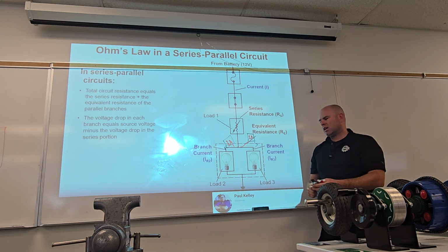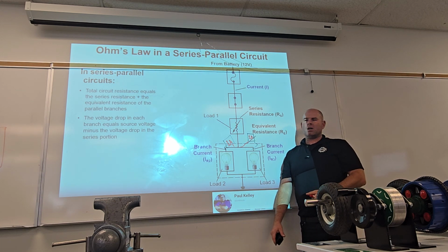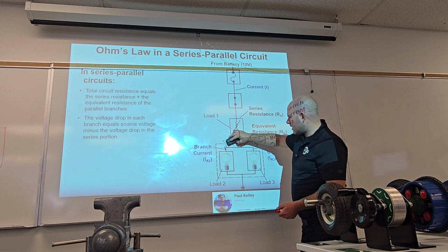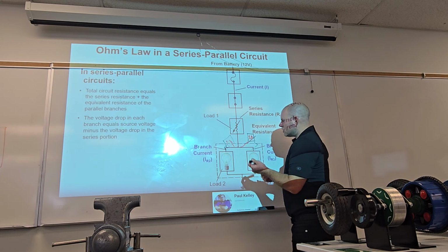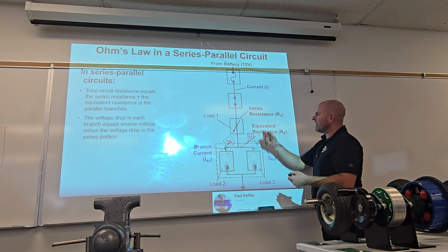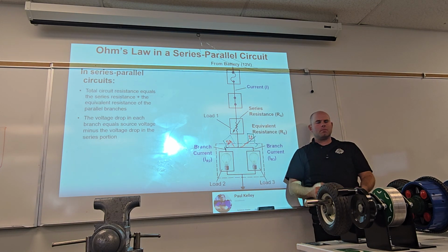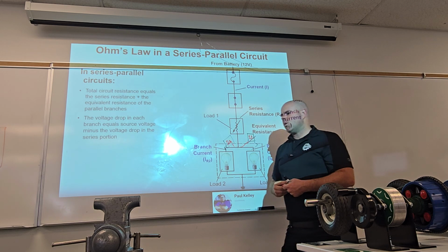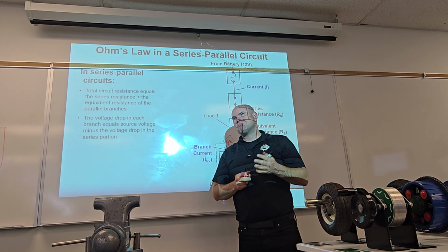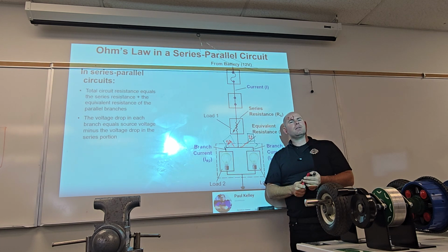In automotive, I'm not sure that we'd ever really do this, but if you wanted to get kind of tricky and you were to have 2 amps over here and 1 amp over here, how much was there up here? Exactly. See, it's not even that complicated. It's pretty simple. Why you'd really want to measure amperage on this, I don't know. It'd probably be more like if you have a fuse that's blowing or something.